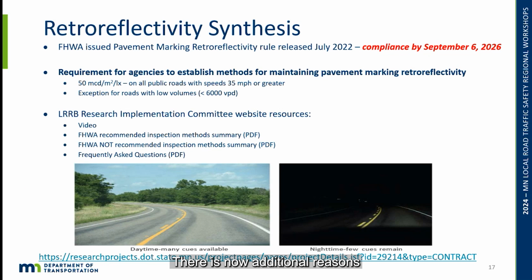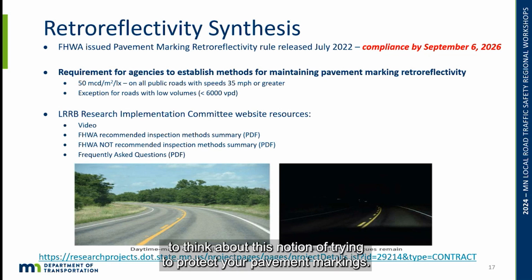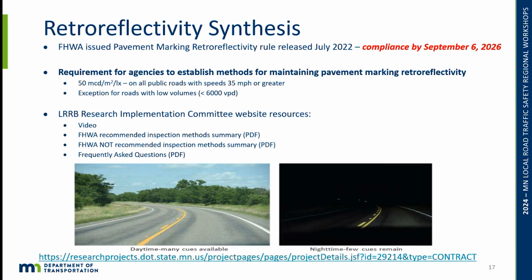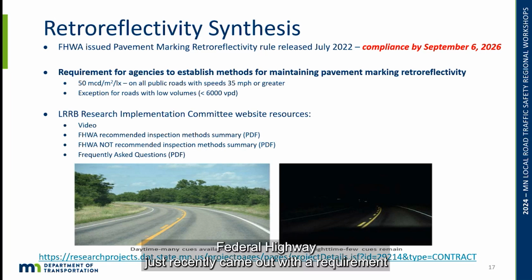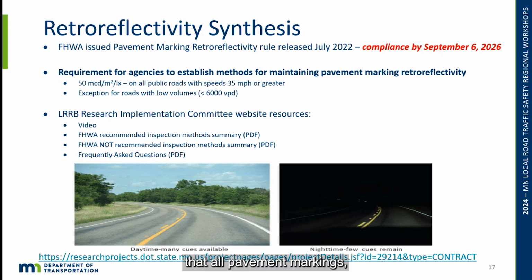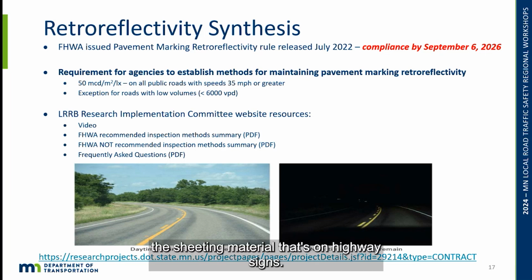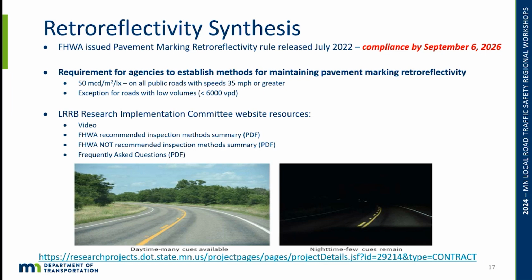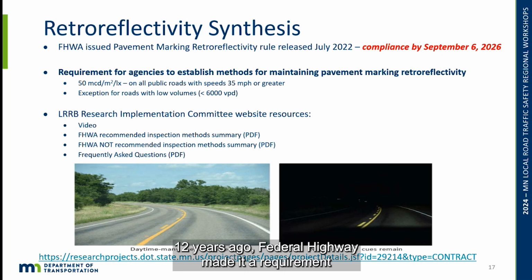There is now additional reason to think about this notion of trying to protect your pavement markings. Federal Highway just recently came out with a requirement that all pavement markings maintain minimum levels of retroreflectivity. This was not a requirement before, and it's similar to what Federal Highway did with the sheeting material that's on highway signs. 12 years ago, Federal Highway made it a requirement that agencies that put signs up maintain minimum levels